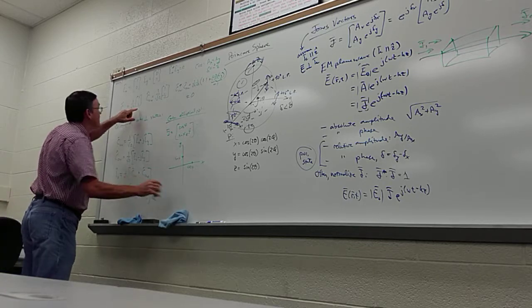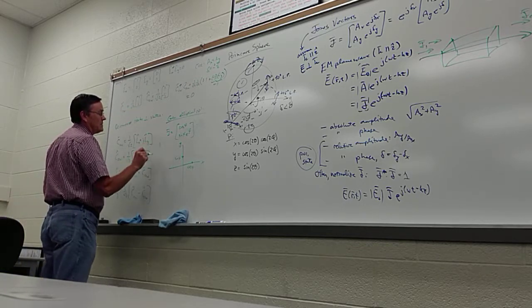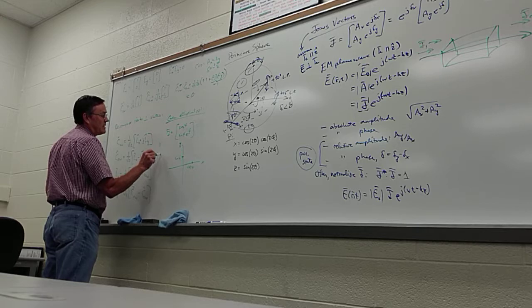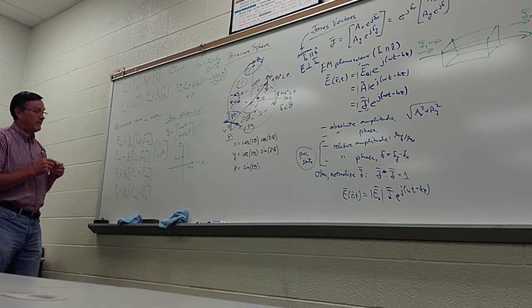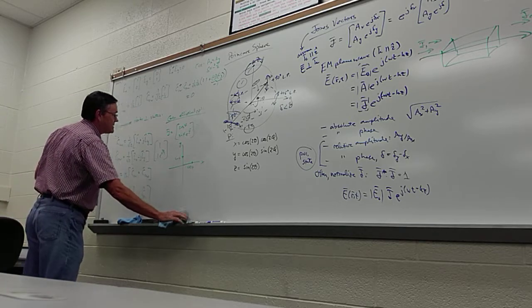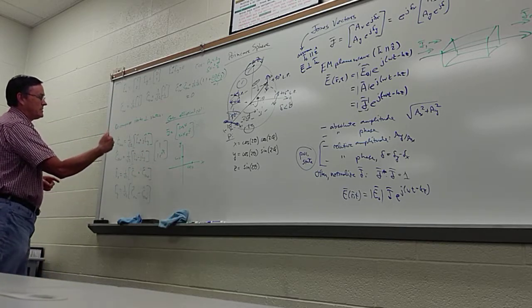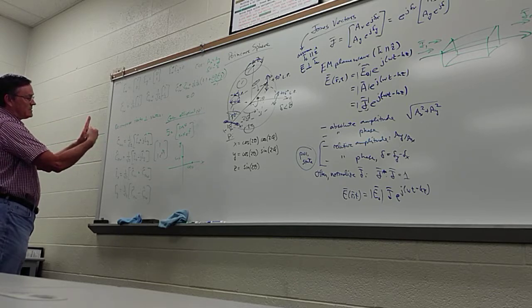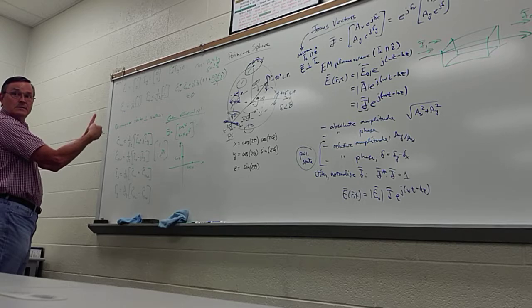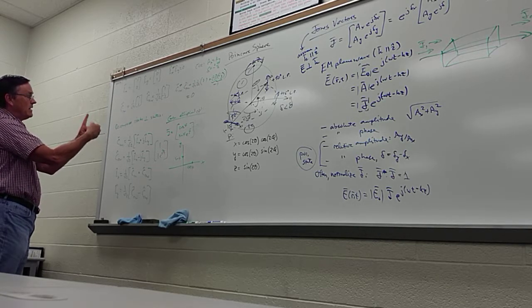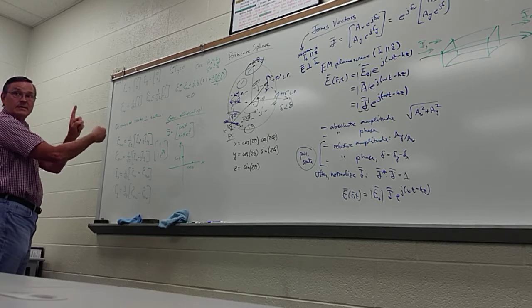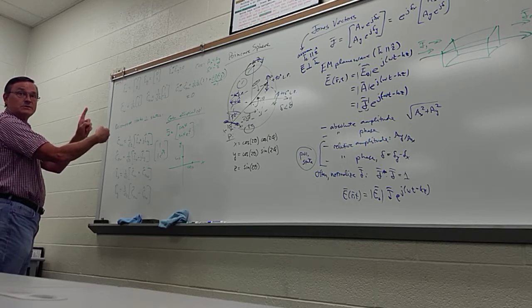That's the same as saying 1 and 1 e to the j pi halves, right? Same thing? Okay, so I look at this and I say, here's the x component, here's the y component, and I'm shifted forward by pi halves, right? So y comes before x by pi halves, and I'm not going to worry about the exact amount, I just know it's pi halves.